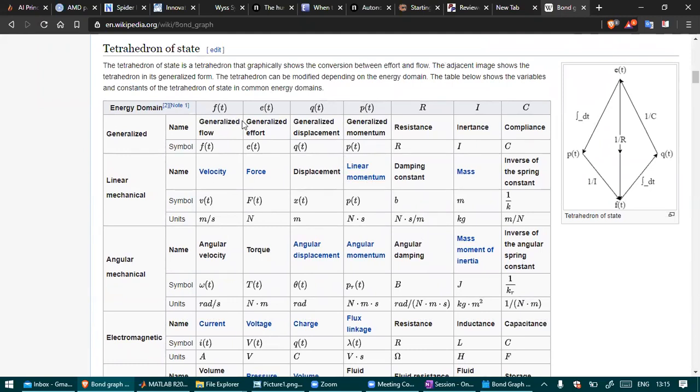Okay, we won't talk about this, but up to this point, I want to just mention that bond graph works with flow of power. It defines based on the flow and effort, which is equivalent to velocity and force. And secondly, each system can be defined in terms of three elements: a resistance, an inertance, which let's call it mass, and compliance or springs in terms of a mechanical system. Okay, so that's basically the only concepts we need to know.